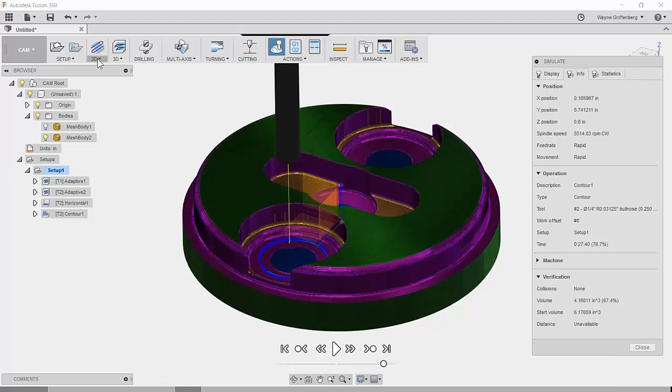It's a great point. I remember early on, in the early days of solid modeling, people would constantly say, well, can you machine a DXF file? When you really prod a little bit, you'd find that a DXF file was generated as an output from Inventor or SolidWorks or Pro-E, and you should just have gotten the solid initially, or at least a neutral solid like a Parasolid. Think of it like it's much better to spend time with a friend than just look at a picture of the friend. And to some degree, an STL file is just a picture of the solid. It's not really the true solid. So we can work on it, but if you can get the native, it's much, much better.